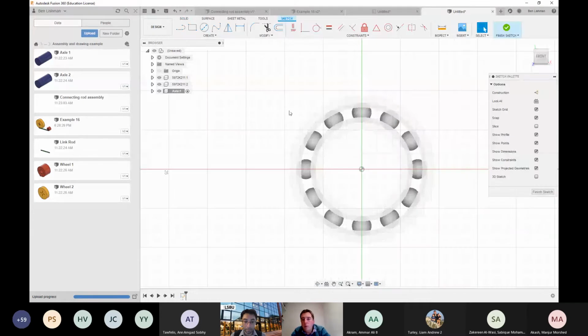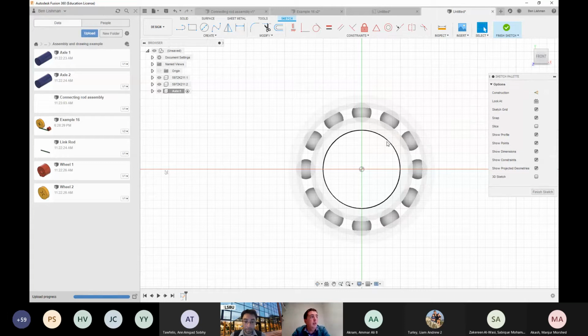I want my bearing to fit very, very tightly on my axle. And we'll talk in future weeks about tolerancing and things called interference fits, where you're deliberately making two things the same size, so you have to almost bang them together with a hammer, and then they fit very tightly and they won't slip against each other. So that's really what I'm aiming for here, in a sense.